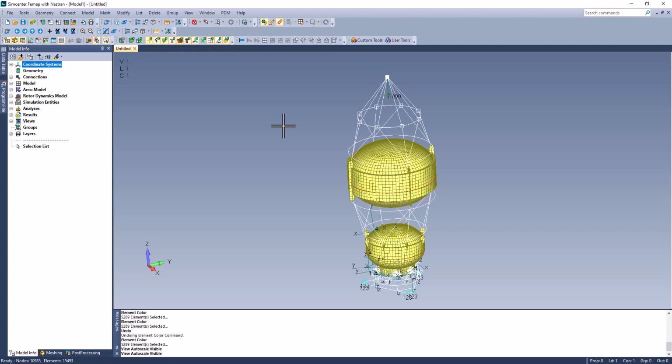The defined fluid mass allows users to model complicated fluid volume shapes and extended fluid volume types, such as volumes with sloshing free surfaces. We can use these capabilities to compute the effective elastic modes of the structure when the fluid is able to slosh. This video will demonstrate that capability.